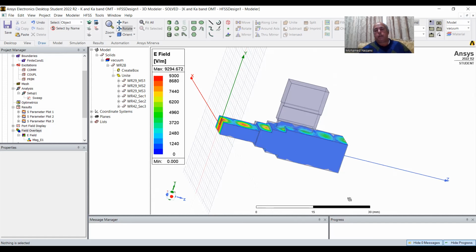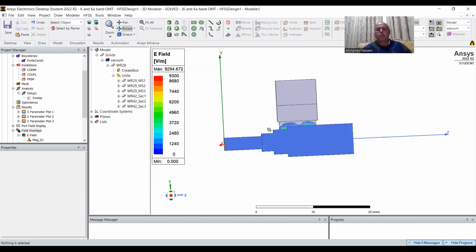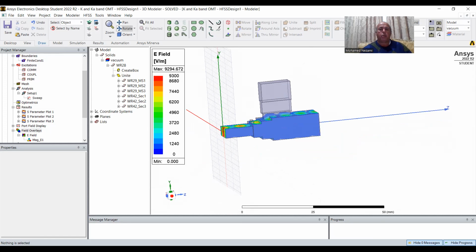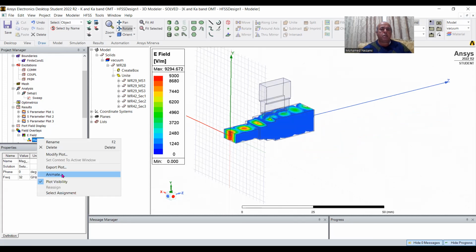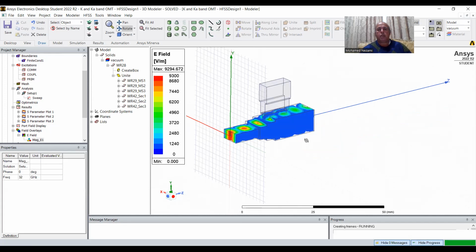Well, in this case, you have the antenna gain, which is about 30 dB, the parabola gain, the antenna itself. So you're dealing with a minus 80 dBm signal and a plus 40 dBm signal. So you would want at least 40 to 50 dB of isolation between these here. And that is obtainable with this design, of course. So let's animate this and just watch what you're seeing in here.